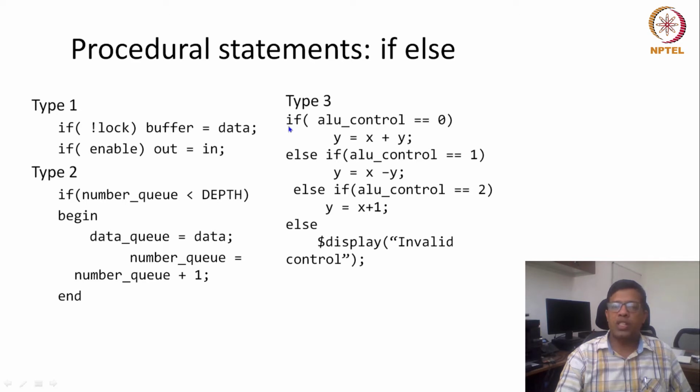You can see this particular syntax is also quite similar to the syntax of C or C++. The only difference is that if we have multiple statements in this if block, then we'll use begin and end. Otherwise, there is not much difference. In the end of this logical if else ladder, we can end the ladder by else.